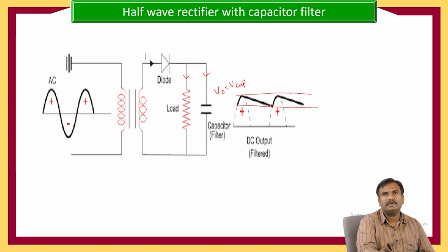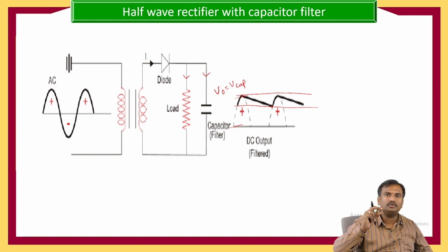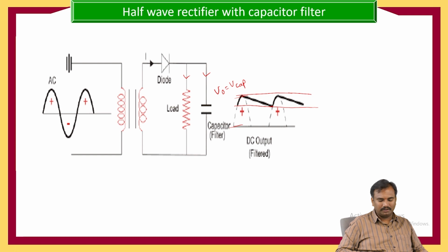You can see previously we had these pulses in the output waveform. Now here the pulse quantity is reduced. So if we go on using the next filtration, in that case we are going to get a constant DC.